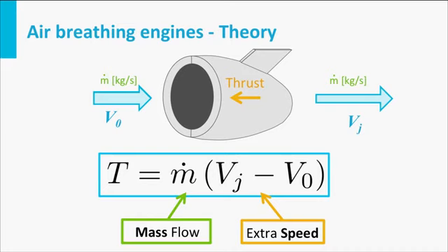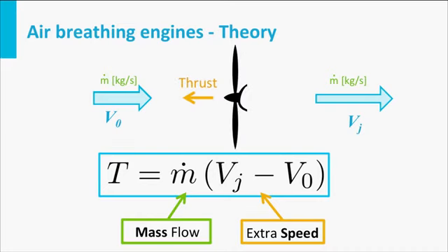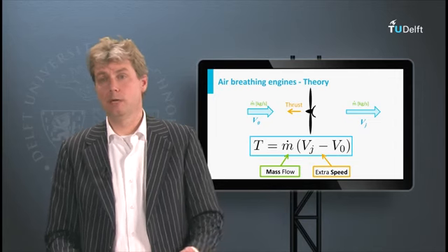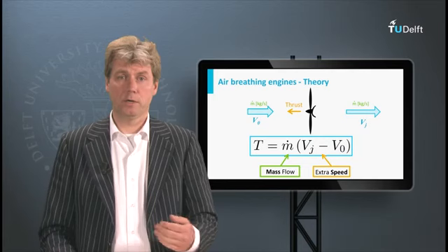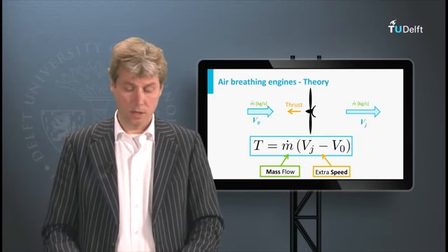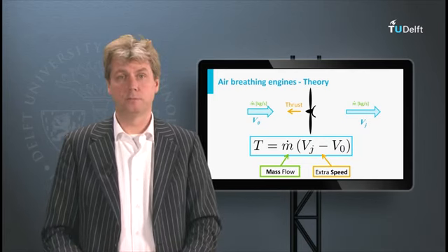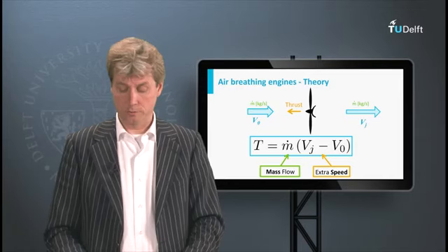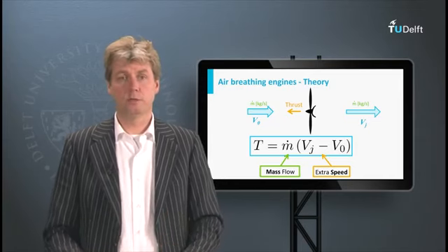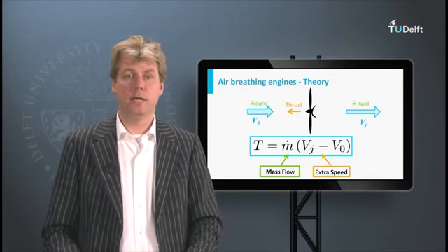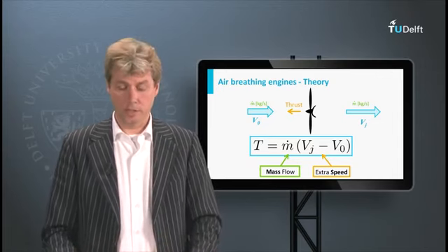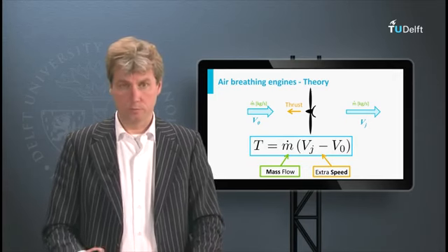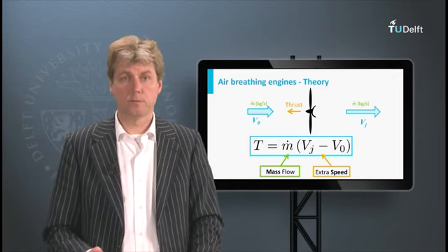And be aware that even though in these drawings we use the jet engine, the same goes for the propeller engine. It's simply the amount of the speed change between the air before it enters the propeller surface and when it leaves the engine, or the propeller surface. So this is the basic principle for any air-breathing engine, any engine that uses reaction propulsion that accelerates the air to create a thrust force.